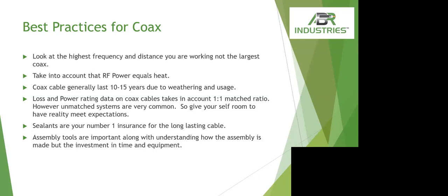Also, understanding your assembly tools. Assembly tools are very, very important. Getting good, high quality tools is always important, but also remember there's a couple of other things associated with that cost. How often do you use that tool? If somebody else has the tool, borrow it from them. Two, the tool is only as good as the blades that are built into it, and a lot of those blades can be very expensive to replace. Plus, a lot of those tools are only intended for about 25 to 50 strips before it starts to wear down. So always take that into consideration as well.